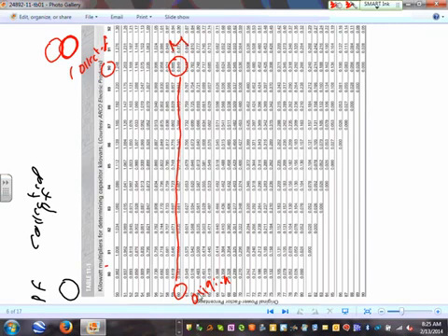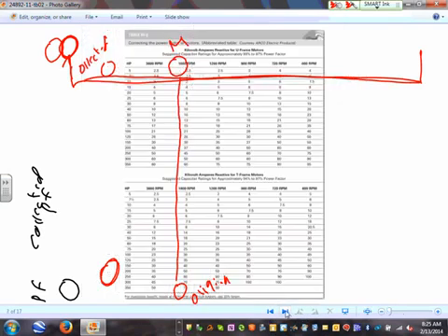You typically start correcting, guys, with 80 or more. You want your power factor higher. Typically, the correction starts right here. That's where you want your correction to be, 90 or more. So if you correct to 90, you are close enough. Okay, so that's the first thing I would like you guys to go over.